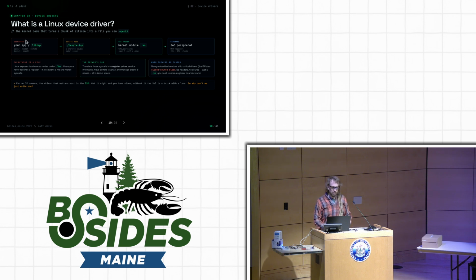Your streaming application on these Ingenic devices talks to a user space library called libimp. It's closed source. It speaks to the /dev/tx-isp driver in the kernel space, which is also a closed source driver. And it understands how to communicate with the actual hardware in order to set up the device and the video streaming pipeline.